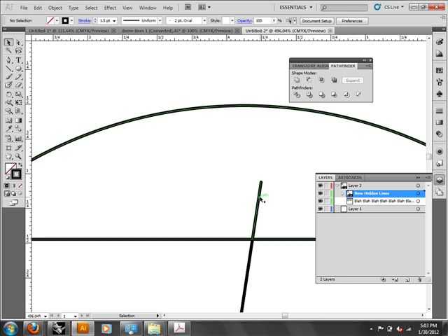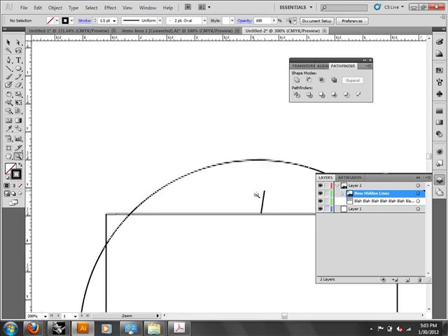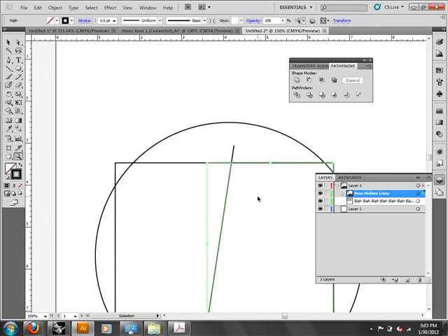Can you toggle through the scissor, like which line to pick? Well, you have your choice of which ones to pick once it's been cut. So I could take out the one side and not the other side if I wanted to. I don't know if that's your question. No, I mean when you're choosing where to cut it. Oh no, you don't choose. That's the thing about Pathfinder. You don't choose where to cut it. It just makes every intersection a cut. Scissors, you actually click on it.